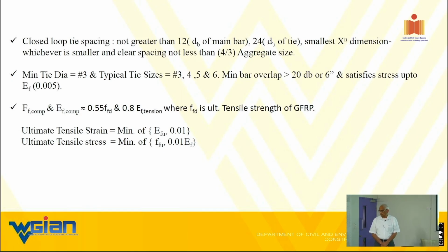Actually, the specimens should be tested under triaxial pressure. Right, to get the real, correct value. But again, if you're going to test a concrete with FRP bar and put a gauge on the FRP bar, then you get a very realistic value. And what I'm saying is, those numbers will be much higher than that.